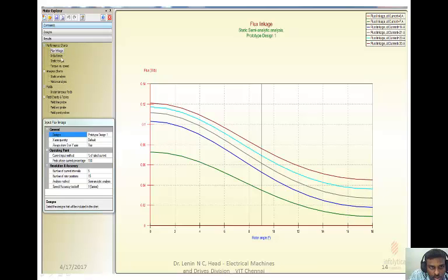So we can do this separately, as well as we can do these two things separately. And apart from this static and motion analysis, we have instantaneous fields. We have field line probe, field arc probe, and field point probe. That means we can probe the flux density and field intensity separately. So initially what I did is we will go for the performance chart and check what is the flux linkage, inductance, static torque.